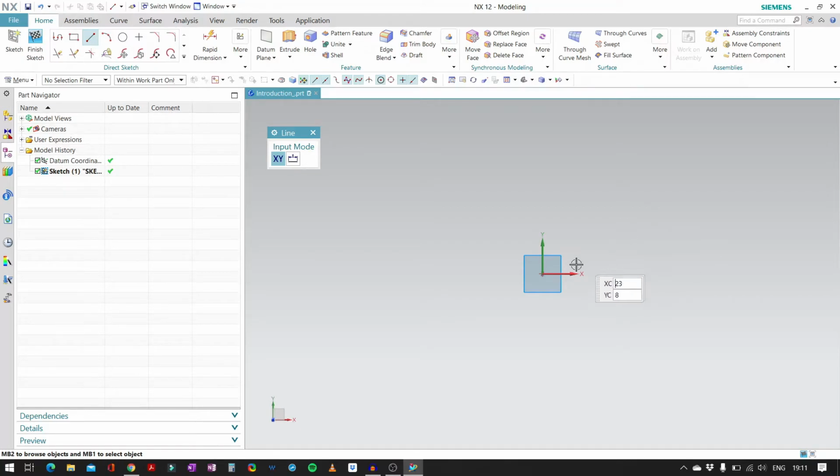I'll do it straightforward. If you hover over it, let's say there are two lines upon each other, and when you are seeing from top view, you are sketching on it. There may be a question of how to choose the middle line or the bottom line. You can go to that line and wait.